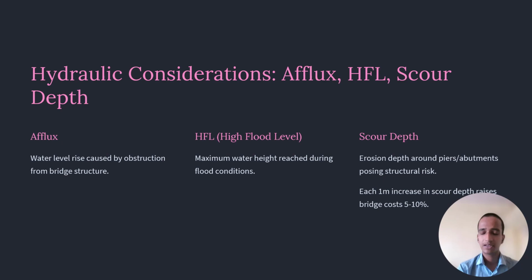And lastly, the scour depth. Scour depth is the amount of excavation done while building a bridge. The lesser the scour depth, the more cost effective the bridge is. But also we should not compromise with the quality of the bridge. So keeping both things in mind, we should construct the bridge. And as a fun fact, each 1 meter increase in scour depth raises the bridge cost by 5 to 10%.